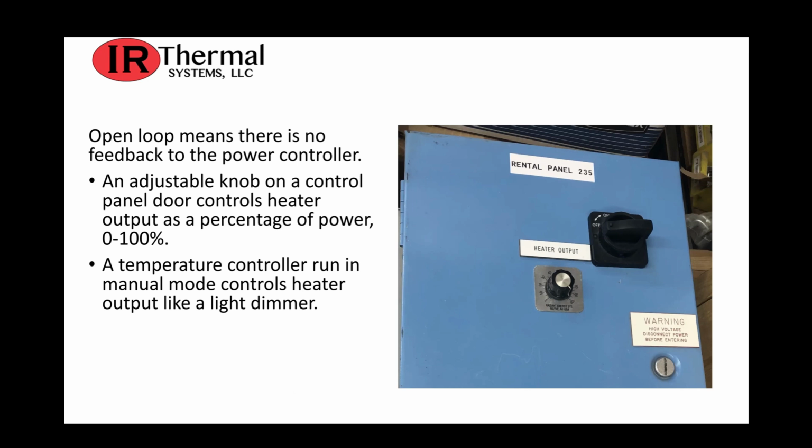So like shown on the right there, you have an adjustable knob on a control panel on the door that controls heater output as a percentage of power, 0 to 100%, like you can see there. And the temperature controller is run in manual mode, and it controls heater output like a light dimmer. So you're basically adjusting the temperature yourself, and you're really not getting any feedback from the process of what's actually happening there. You're just sending the signal, sending the heat out to the field.